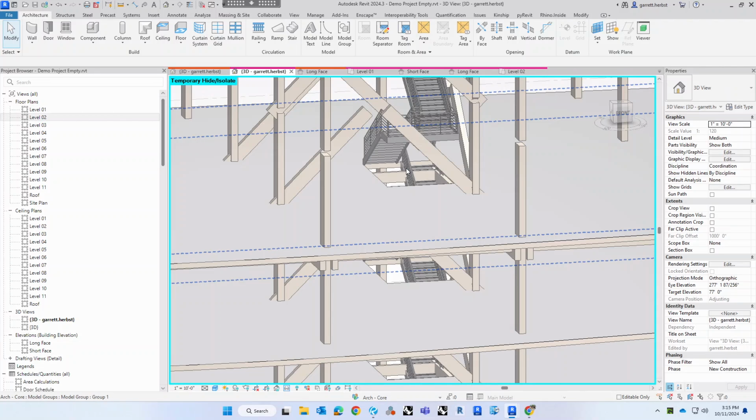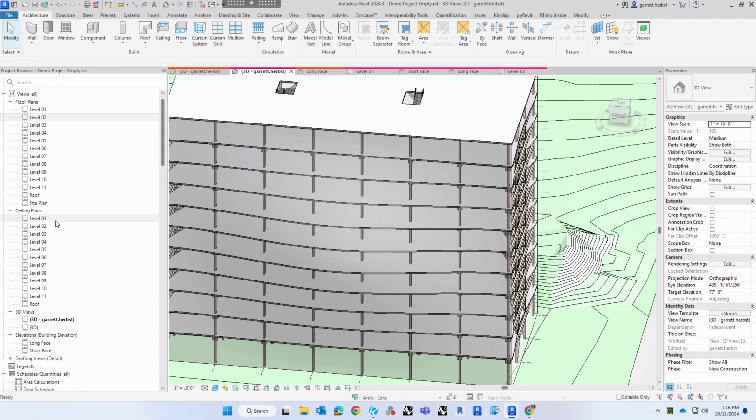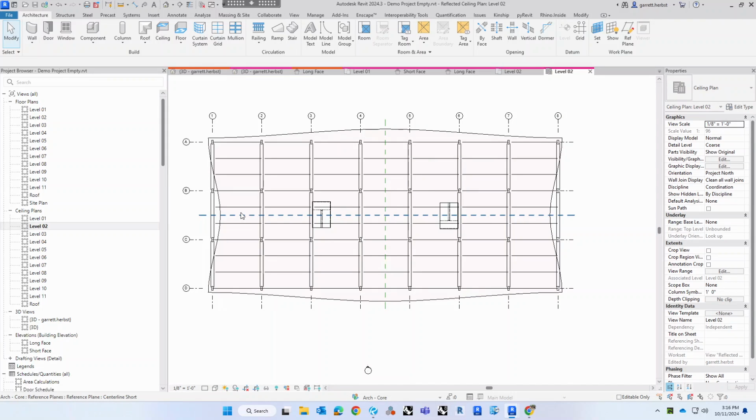So you want to make sure that they're within a column grid. That way it's much easier for the structural engineer to frame around it. As we talked about last week, CLT panels can be used as shaft walls. It adds stability. They can act as shear walls. So if you wanted to, you could create your stair walls out of CLT panels and use them as a structural component, and actually have your beams abutting and resting, being supported by the CLT.